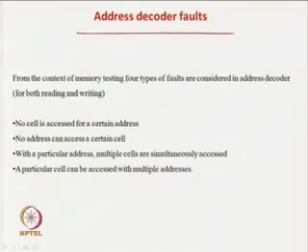The last part is address decoder faults. Address decoders are nothing but another type of combinational circuit, and we do not test them in a normal manner like a combinational circuit, because they are coupled to a memory. Its job is only to access some memory locations and deliver the value by the sense amplifier and the driver cells.